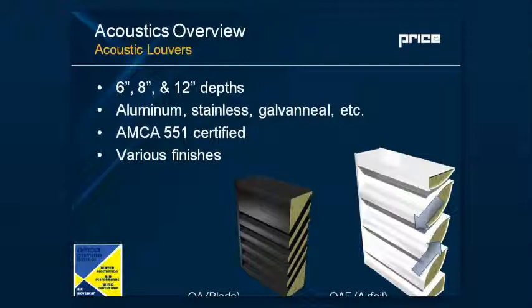And so what they're doing is they're taking the insertion loss value of the acoustic louver and they're adding 6 decibels to it because they're saying, well, you're not going to push an acoustic louver up against a piece of equipment and you're not going to have a person pressing their ear against the other side. So in effect, you're getting a noise reduction and more than just an insertion loss sort of performance out of that louver. So again, that's just going to increase all of the insertion loss values by 6 dB when you do that typically.